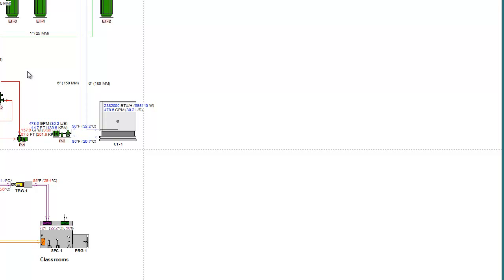And then you know how to connect the components in the 3D Revit model. And the data from HVAC solution can be put in the shared parameter data of Revit. And then you can use the Revit schedules format, which we automatically create for you in Revit, to have your schedules created in Revit. So this is what HVAC solution does.